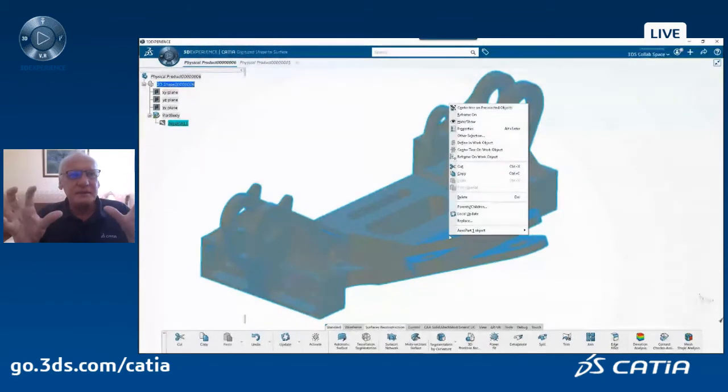The ability to import billions of points is only in 3D Experience CATIA. The ability to recognize planar surfaces automatically is today only in 3D Experience CATIA, not in V5. But the rest, everything I showed, was also available in CATIA V5. In 3D Experience CATIA, the app is called CATIA Digital Shape to Surface. And in V5, it's called Quick Surface Reconstruction, and Digital Shape Editor for the add-on being able to import the points cloud. Here, it's also a very interesting command. I really like it. It's also a magic command, I would say. Only in 3D Experience CATIA for this one.